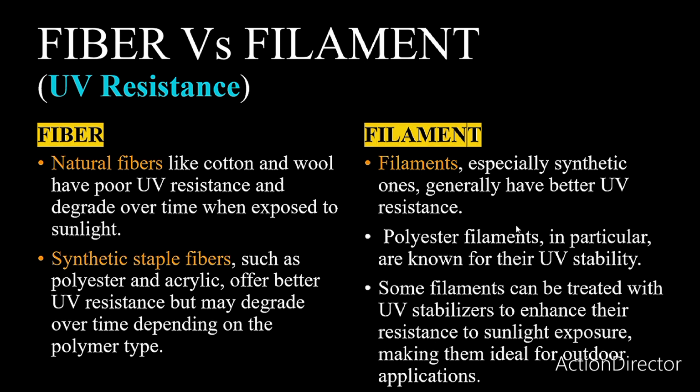Polyester filaments in particular are known for their UV stability. Some filaments can be treated with UV stabilizers to enhance their resistance to sunlight exposure, making them ideal for outdoor applications. So filaments have better resistance to acid, alkalis, and UV.